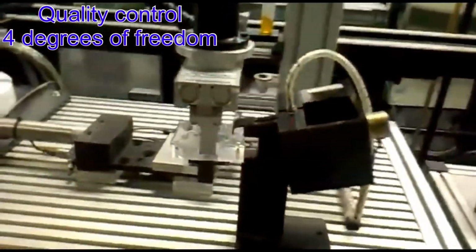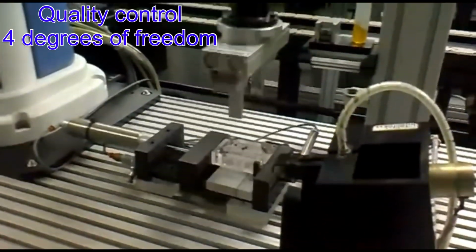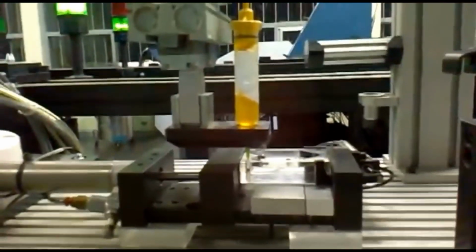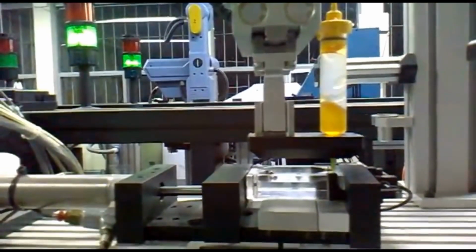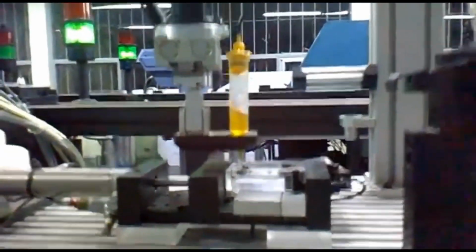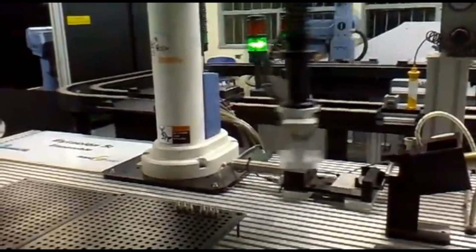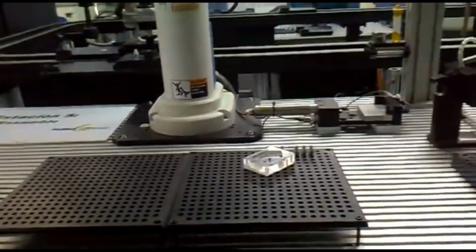The last station is where the quality control is located. The piece is received and the camera is turned on to identify errors or any issue with the specification. If it's wrong, the piece is sent to the scrap, or if it's okay, it is defined as a finished piece. It also has an assembly station inside of it, where the SCARA robot can create special pieces like the one that is on the video right now, and it's one of the simplest robots, but it's really efficient.